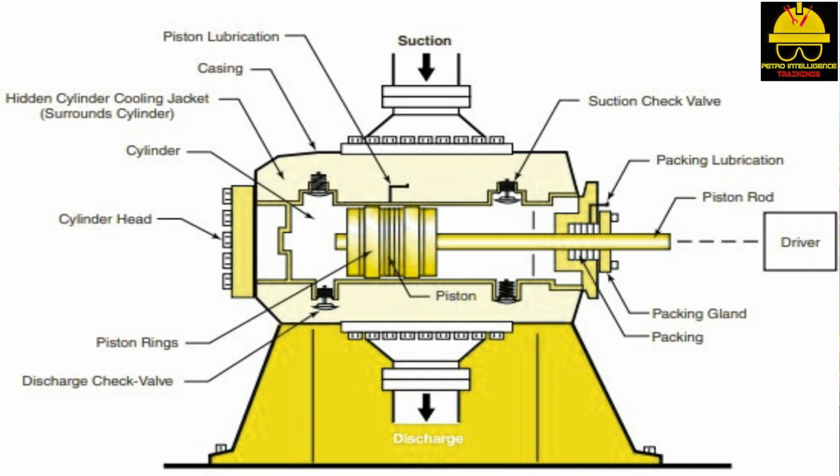There are several advantages of using a reciprocating piston compressor. They have a flexible pressure range and overall capacity, low power cost, and high efficiency rating. They can handle density and gas composition changes and small volumes and can deliver high pressures. Reciprocating piston compressors work by trapping and compressing specific amounts of gas between a piston and the cylinder wall.